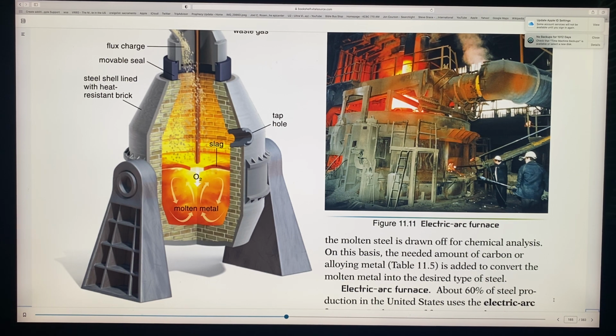The molten iron in there is agitated with this oxygen blast that comes in at 1,650 degrees. And the reactions are very rapid. It takes about half an hour there, and lime is added for the slag, and a sample of steel is drawn off and then analyzed to see if it's just what they want. And then on to another type.